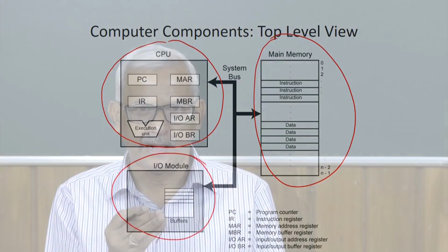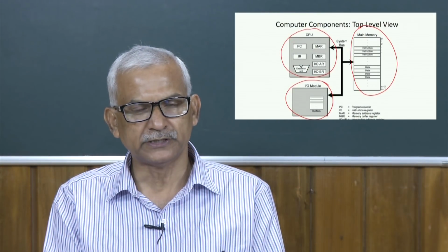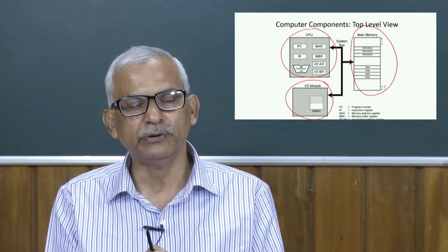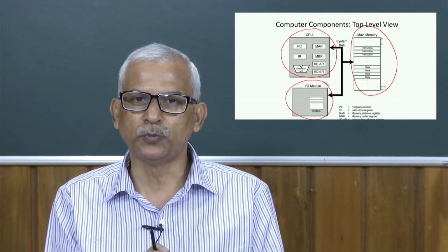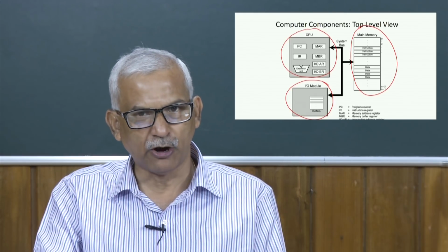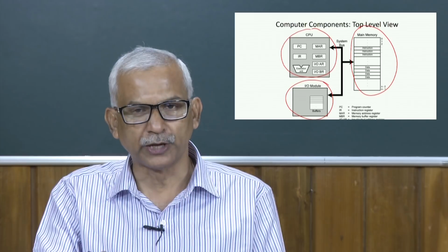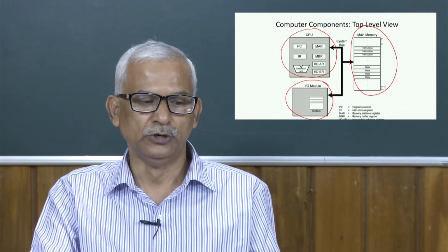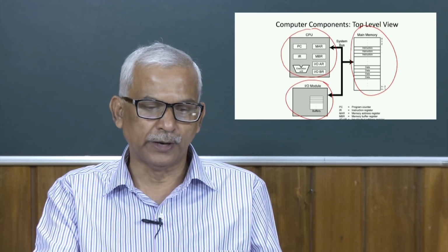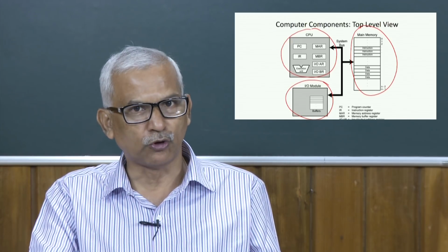If I have an address bus of 32 bits, we can connect a memory with 2 to the power 32, which is 4 giga memory locations, and depending on the size of the data bus, we can say how many bits we can store in a particular memory location. This is basically connecting the other components with the processor to build a full computer.